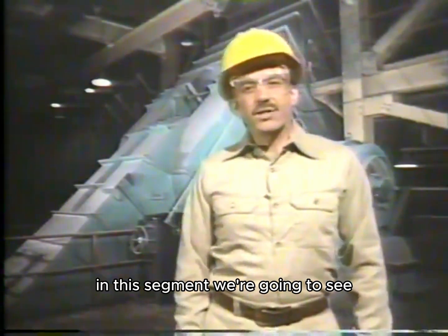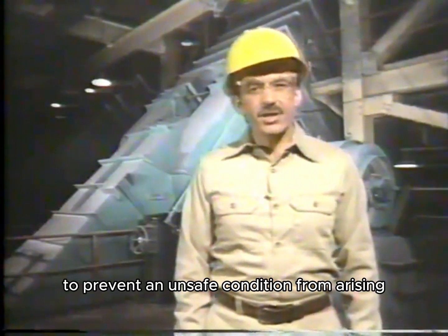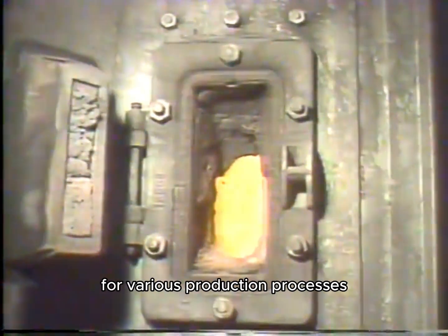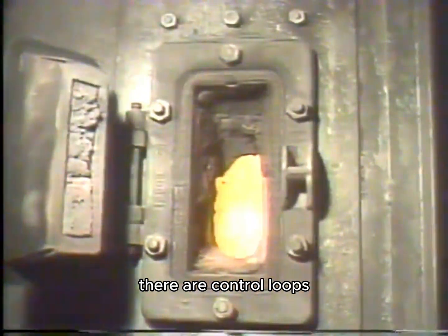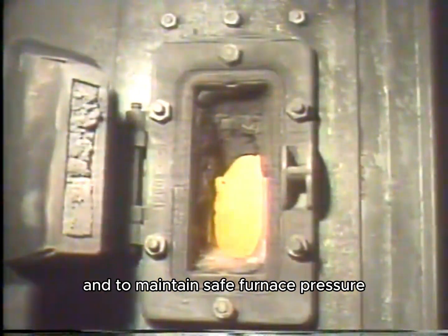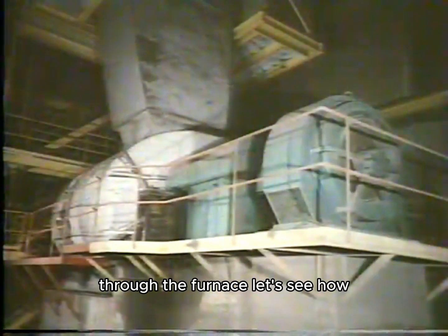In this segment, we're going to see how a feed-forward control loop can be added to a typical feedback control loop to prevent an unsafe condition from arising. For example, many industrial plants have furnaces that provide heat for various production processes. In the operation of a furnace, there are control loops to maintain the combustion process and to maintain safe furnace pressure. Both of these control loops can be related to airflow through the furnace.